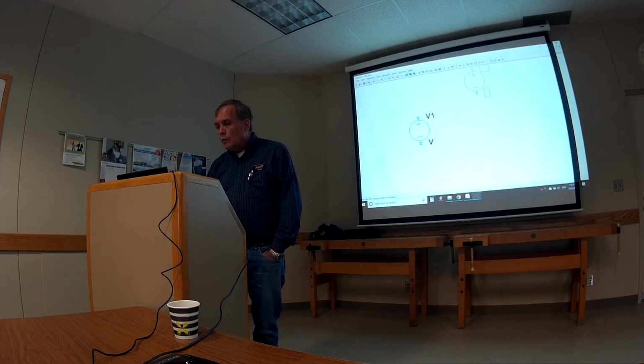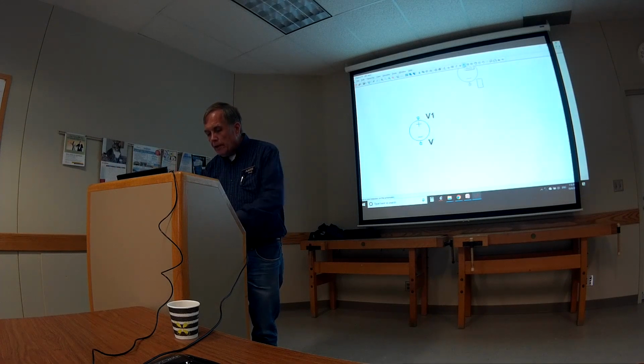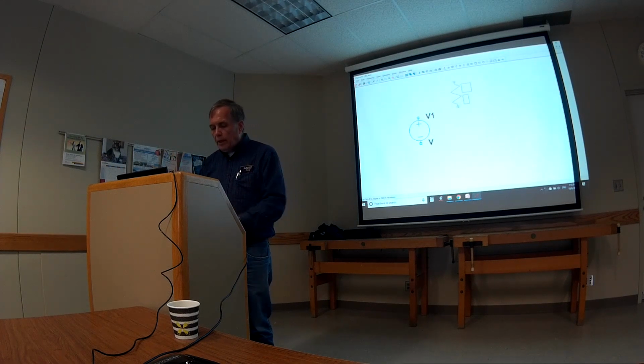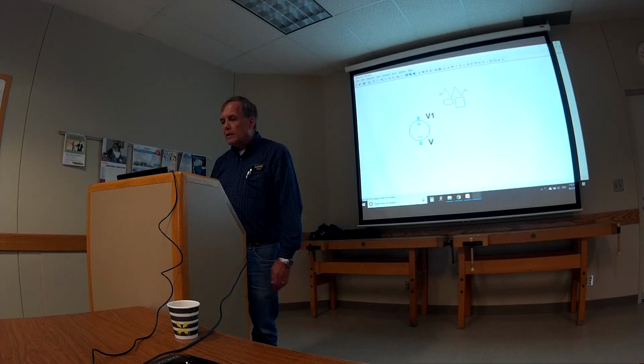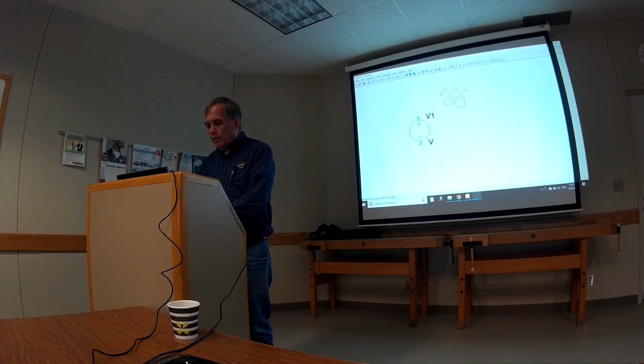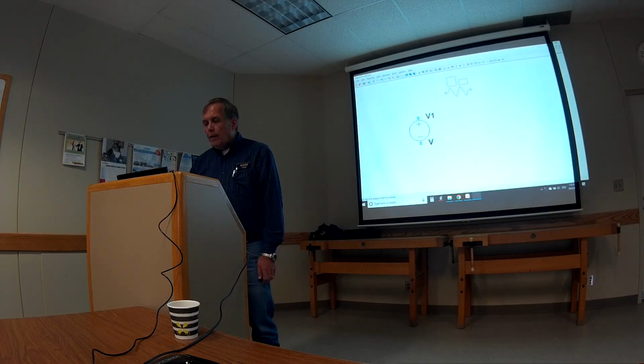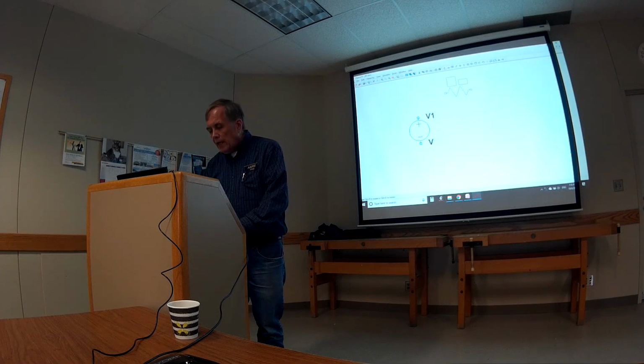And I'm going to put just two other parts right up in the top bar here. There's a resistor. It's a very common part. There's the resistor here. You bring it down. By the way, to rotate a part, each tool has its own way of doing this, but it's Control R in LTspice. Control R will rotate it around any way you want it. Okay, so I'll leave that there, and then I'm going to get a capacitor up here.